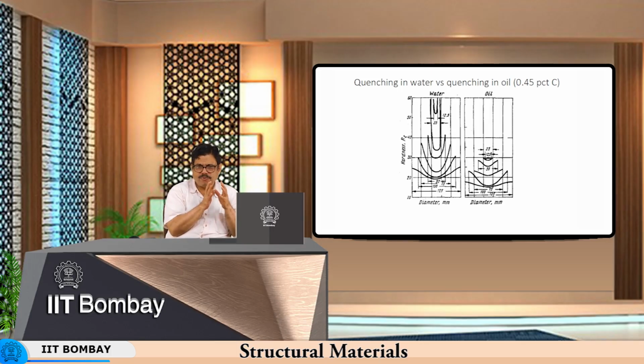That is something which can be achieved using oil. Oil hardening non-shrinking, OHNS, is a very popular grade of tool steel, and it is hardened in oil for a very homogeneous microstructure without any residual stresses induced during the cooling process.